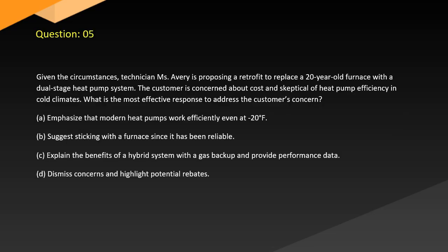Question 5. Given the circumstances, technician Avery is proposing a retrofit to replace a 20-year-old furnace with a dual-stage heat pump system. The customer is concerned about cost and skeptical of heat pump efficiency in cold climates. What is the most effective response to address the customer's concern? A. Emphasize that modern heat pumps work efficiently even at -20 degrees. B. Suggest sticking with the furnace since it has been reliable. C. Explain the benefits of a hybrid system with gas backup and provide performance data. D. Dismiss concerns and highlight potential rebates.